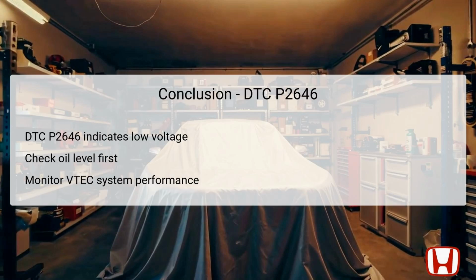In summary, DTC P2646 signals a low voltage condition within the rocker arm oil pressure switch circuit, impacting the VTEC system's ability to function optimally. The diagnostic process emphasizes the importance of checking the engine oil level as an initial step. If the oil level is sufficient, following electrical checks and pressure evaluations is critical for isolating the failure.